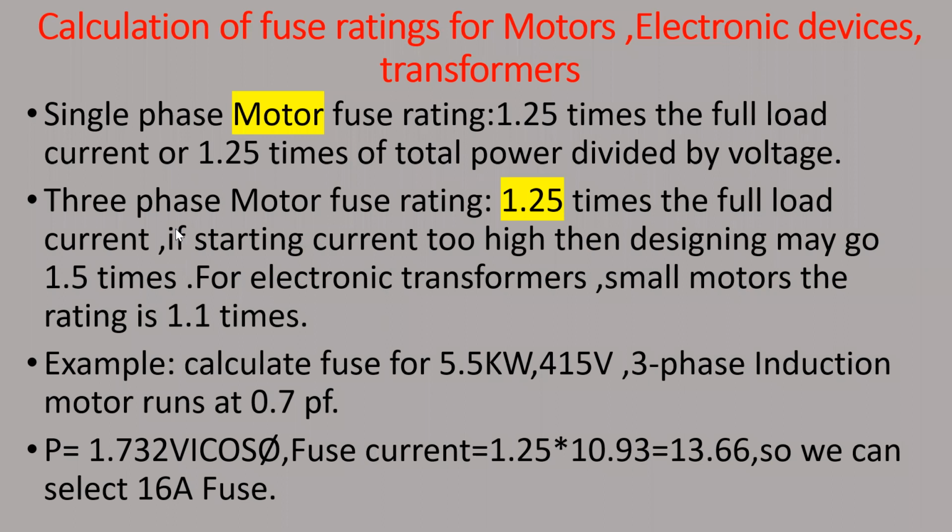Here the first point is single phase motor fuse rating. If it is a single phase induction motor, what should the fuse rating be? It should be 1.25 times the full load current. So what do we mean by full load current?